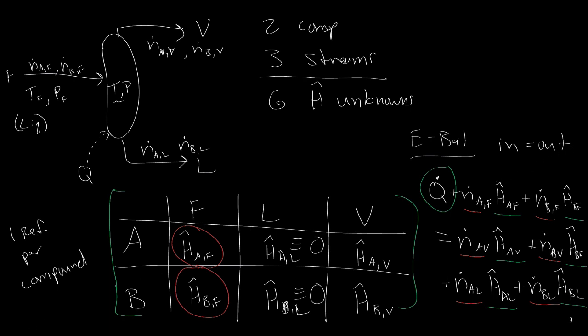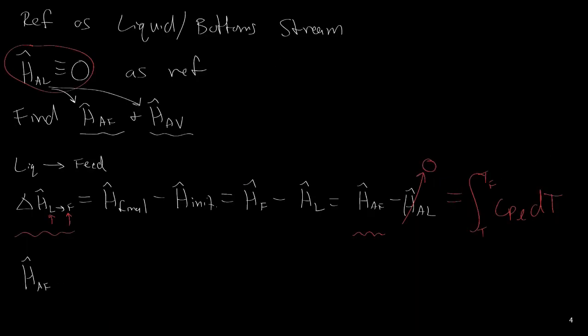So what we're calculating is this particular value here, and what we would fill into our table is the same thing that we have in this delta H calculation, and it works out conveniently that way because we have the reference state canceling out to 0 over here. So what we would fill into the table is the temperature of the liquid and the vapor stream, which is in equilibrium at T. Compare that to the feed conditions of C sub P of the liquid dT, because that's again what we're working with.